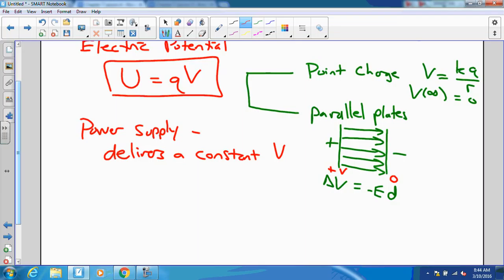But the main point today is that that power supply is going to have to deliver a certain number of electrons, and if we exceed the number of electrons that the power supply can actually deliver, then rather than allow its voltage to sort of vary, what it will do is just shut off. So this particular power supply was, when it was fresh, designed to deliver 13.8 volts for any current load between 0 and 3 amps.